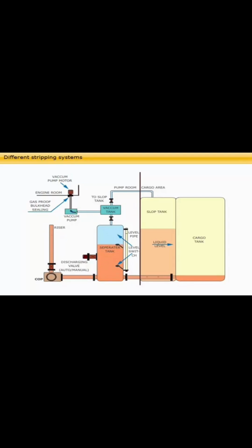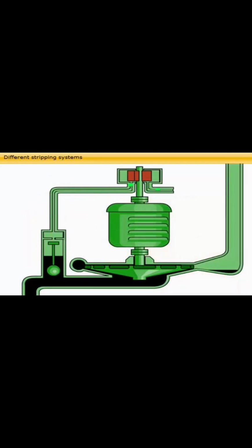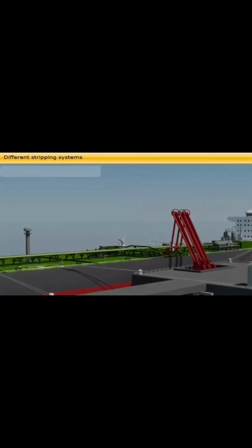As the oil level in the separator rises to a cut-off point, a signal shuts off the valve connecting to the vacuum tank, and liquid cargo is prevented from being vacuumed up. Assisted by the vacuum strip system, the cargo tanks can be satisfactorily emptied by the cargo pumps. In addition, the suction area for the stripping suction bell mouth on double-hull tankers is formed as a sump called the suction well, which allows the suction bell mouth to be fixed inside a restricted area and lower than the tank bottom. For further details regarding vacuum strip systems, see separate documentation.